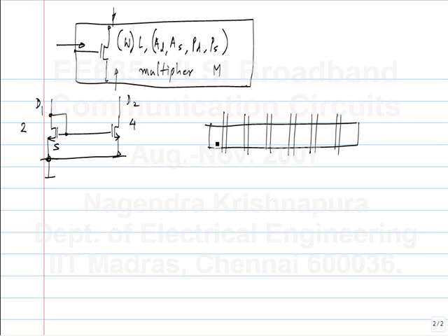So I can do this. This is D1, this is D2, this is D2. And also, in this case, the 2 gates are also connected together, but even if they are not, you can use a similar layout. As long as one of the drain or source terminals is common, you can use things like this. Okay. So this is G1 and G2, which happen to be connected in case of a current mirror.